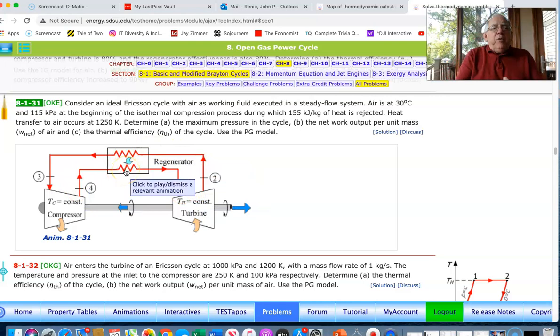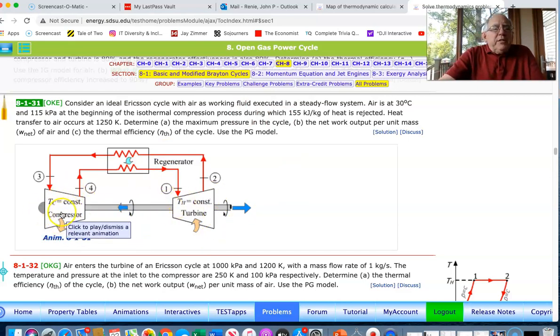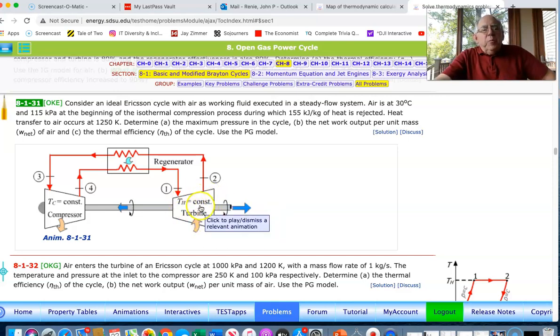With a perfect gas model, we have the same delta T for the fluids as they exchange their enthalpy. So we won't have to set up a device panel for that because we already know all 4 temperatures. Once we determine the pressure for the compressor, we'll also be able to determine the pressure associated with the turbine expansion.